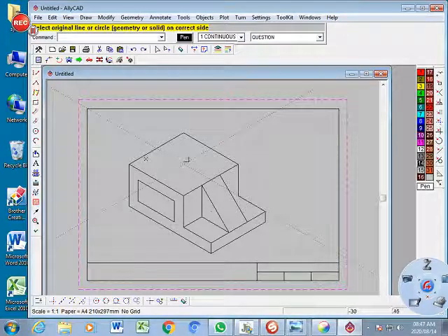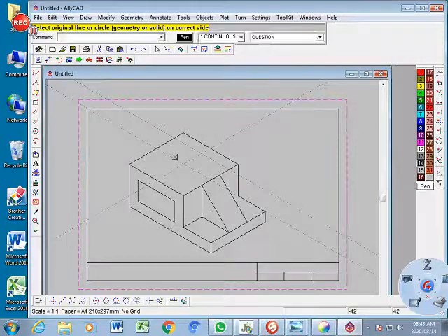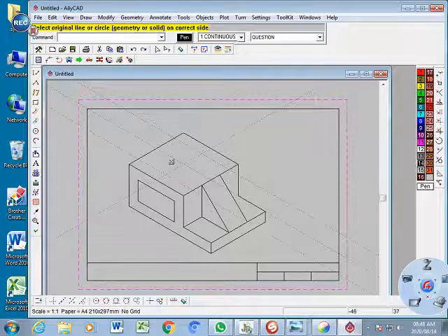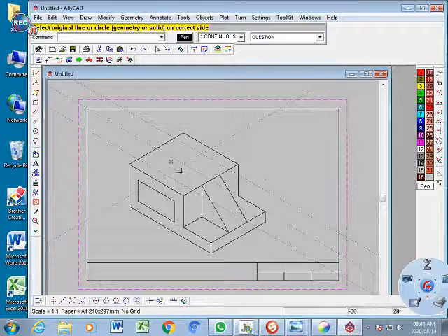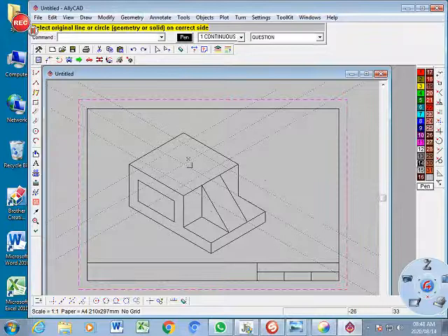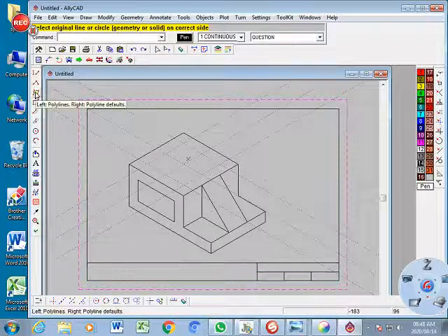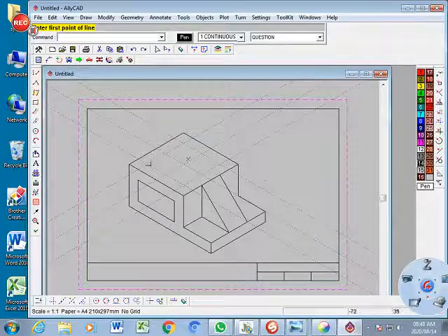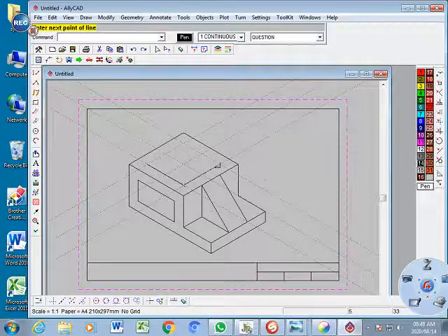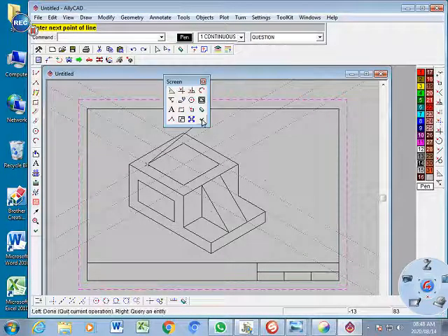Now I'm going to do my box. My circle is 40, so I'm going to go 20 that side, 20, 20, 20. So parallel to that line there, punch in 20. I say yes, and this side 20, yes, and then I'm going to move it to this side of my line, 20, yes, and then that side of my line, 20, yes, and there I've got my box. Let me put in that box for you so that we can see. There we go. So this is my box. What I don't need I can remove later on. Right, that's my construction of my box.